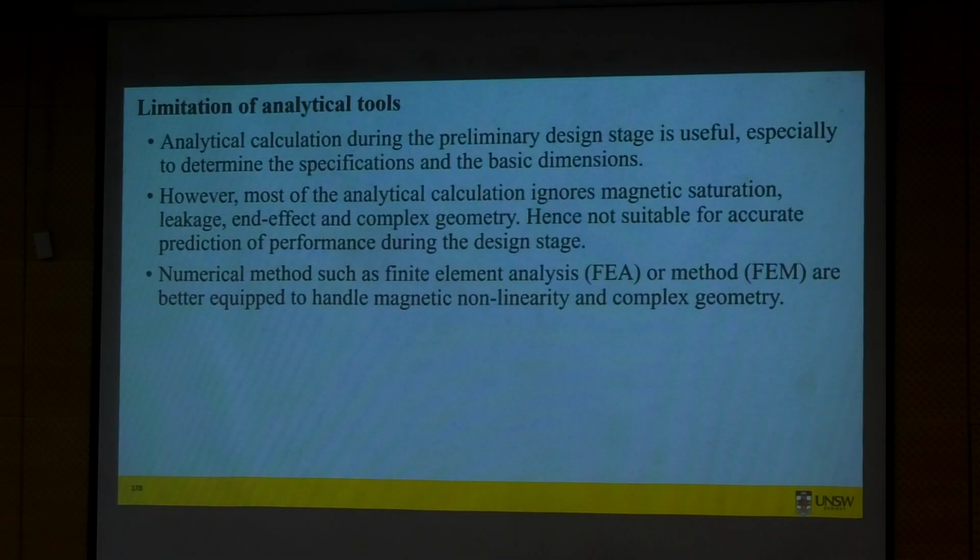We could use an analytical method to find out what the air gap flux density is for this geometry. Am I getting 0.85 or the 0.8 that I assumed? Or what is the torque that I am going to get from this machine? So you can do further analytical calculation for performance verification.